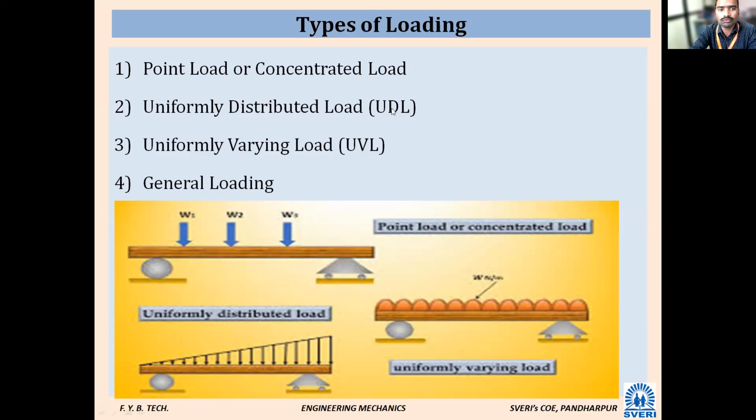Then how do we convert a UDL into an equivalent load? Can you tell me how to convert UDL into an equivalent concentrated load? It is the intensity of load, W, into the span length of the UDL. This will be given in kilonewtons.